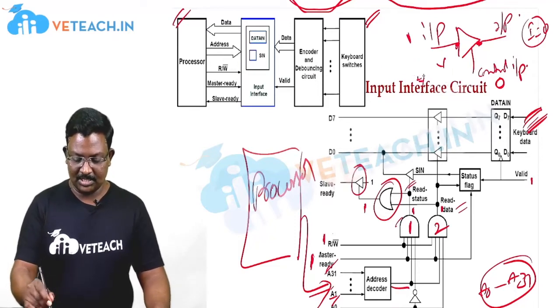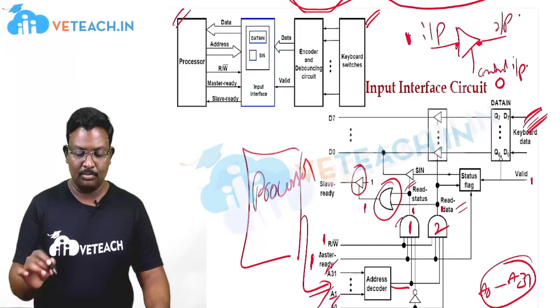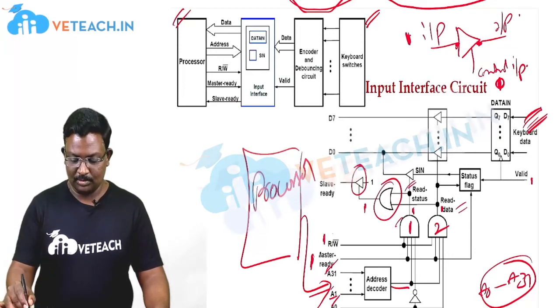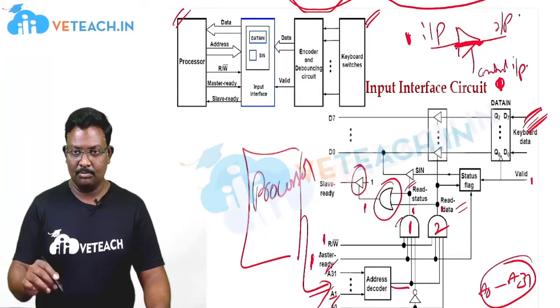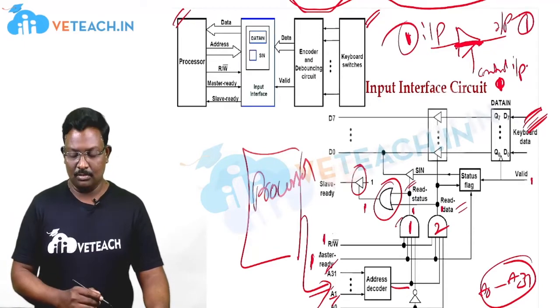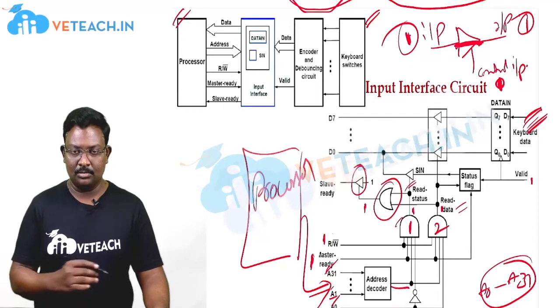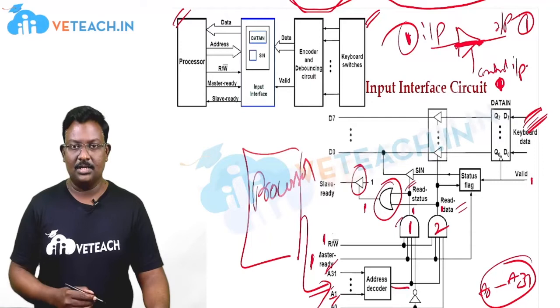Now consider the other case: if we provide input 1 and the control input is also 1, the tri-state buffer acts as a short circuit. It transfers this 1 onto the output side. We have a closed path from input to output, and we are performing the data transfer from input to output.